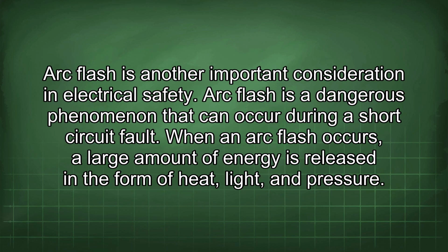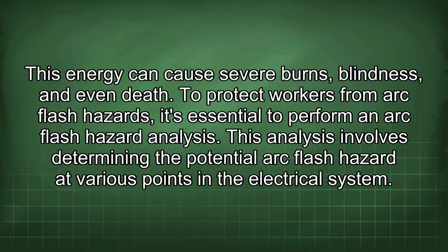Arc flash is another important consideration in electrical safety. Arc flash is a dangerous phenomenon that can occur during a short-circuit fault. When an arc flash occurs, a large amount of energy is released in the form of heat, light, and pressure. This energy can cause severe burns, blindness, and even death.